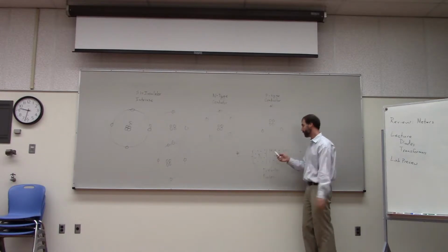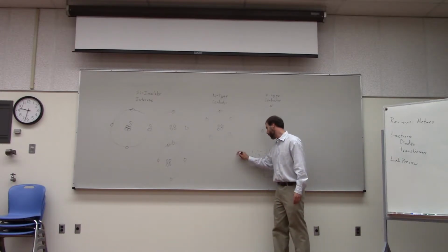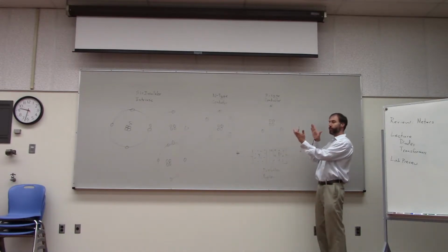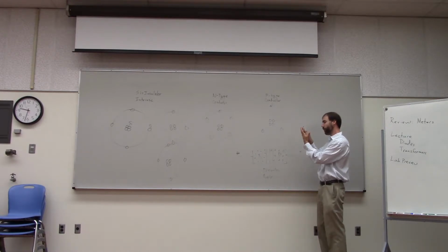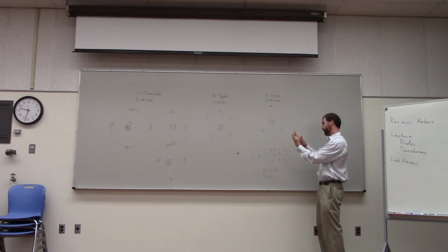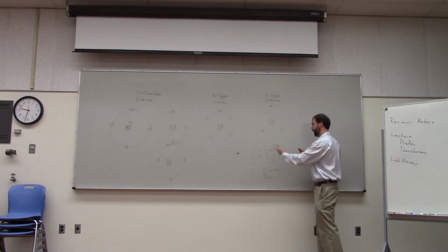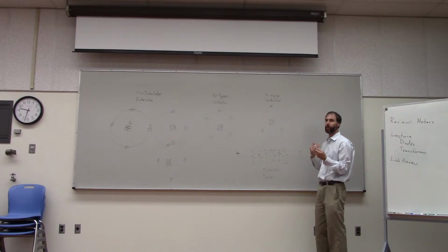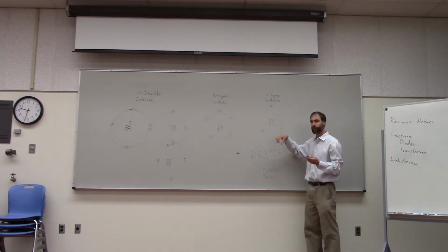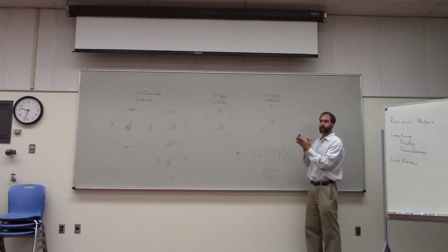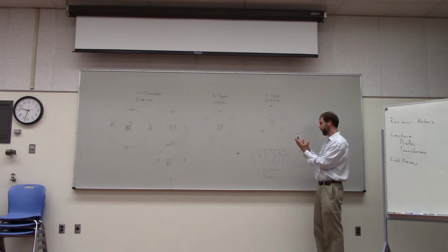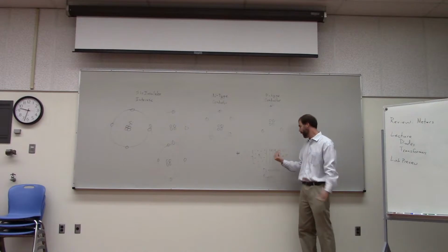It's getting smaller and smaller. It takes about 0.6 volts to completely get rid of this depletion region. Then you have just two conducting forms of silicon and electricity can flow. So that's where the 0.6 volts comes from. And that's why it doesn't really matter how much current is flowing through there. It just takes the same amount of voltage, right?